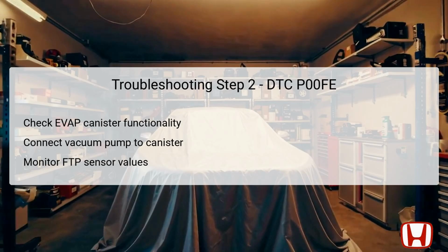It's crucial to apply a specific amount of vacuum to the hose, precisely 1.3 kilopascal, which equals 0.4 inches or 10 millimeters of mercury. Be mindful not to exceed this vacuum level, as doing so could risk damaging the fuel tank pressure (FTP) sensor, which monitors pressure within the tank.